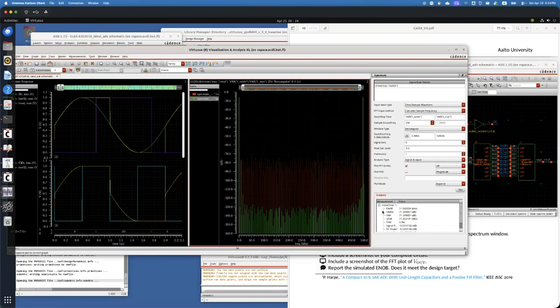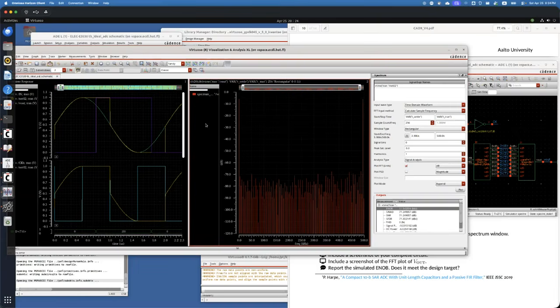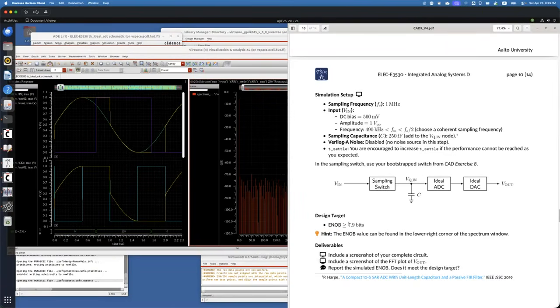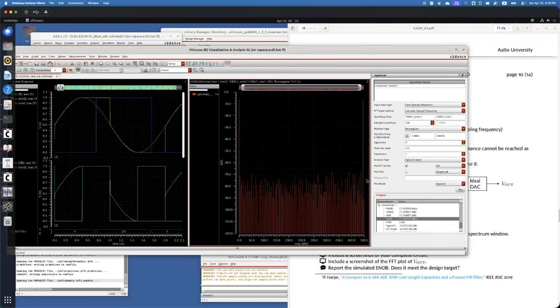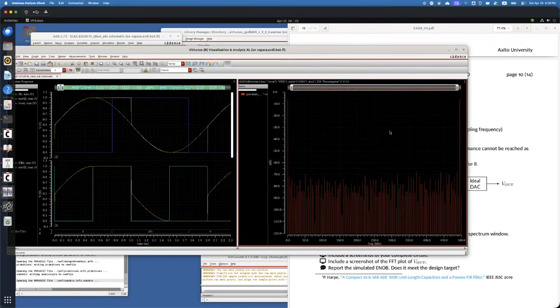Here it says 11-bit, which just doesn't make sense to that extent. The sampler itself can guarantee very high linearity in terms of effective number of bits. So we verified that it is higher than 7.9 bits in our red curve. This one is the data about the green curve, so we can just close it.